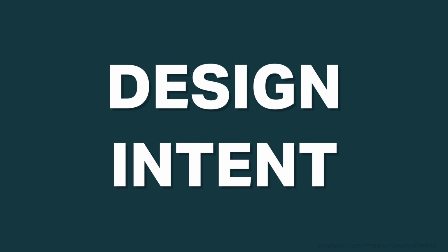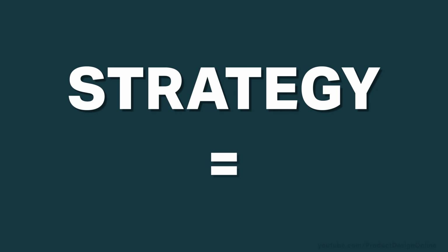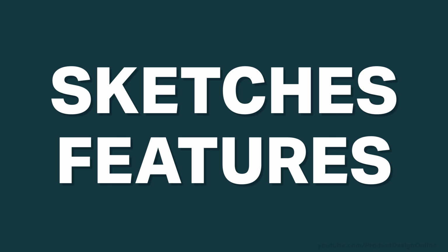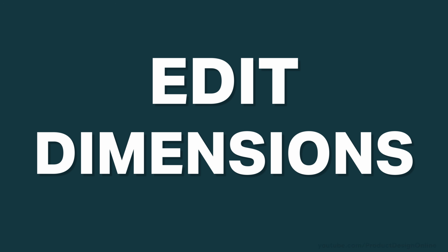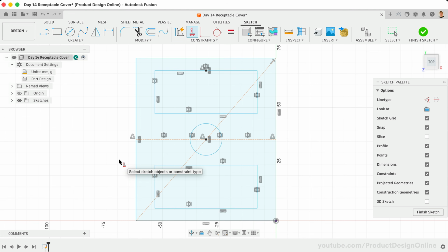Other than that, you should build your sketches based on your design intent, or the strategy of baking intelligence into your sketches and features so that when you edit a dimension later, the model scales, shifts, or updates exactly the way you intended. Press Escape to clear any commands.